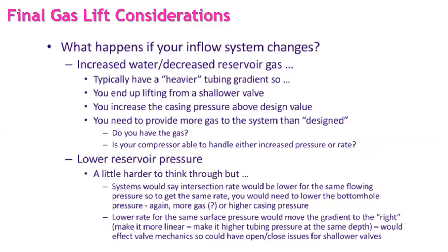So the question in this case is, do you have that extra gas, or is your compressor able to increase the pressure or the rate? So those are questions that we face at any moment, and we have to be ready to answer them. And the other situation is, of course, it's natural that we lower the reservoir pressure. Maybe the pressure drop is higher than we were expecting. So what to do in this case?